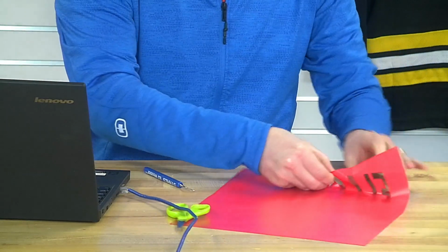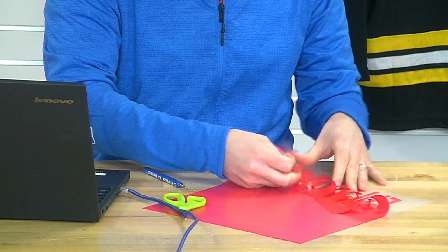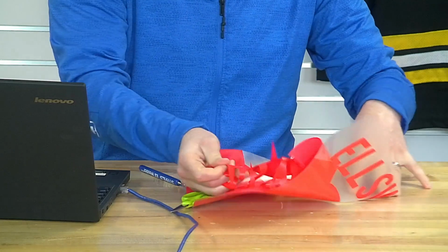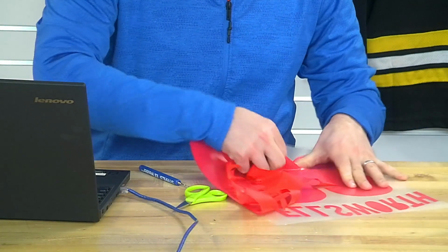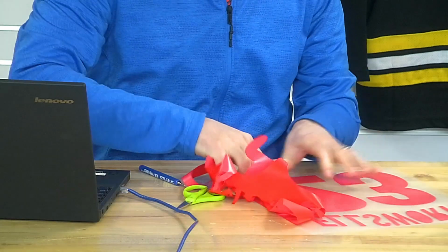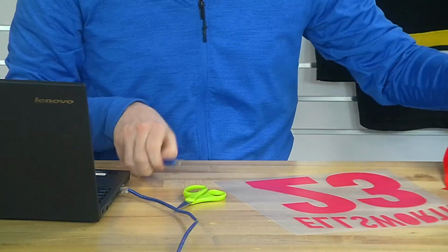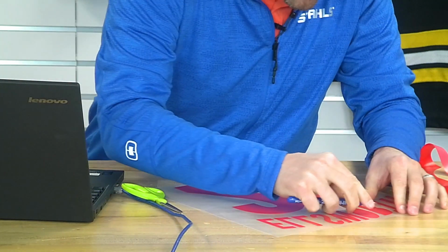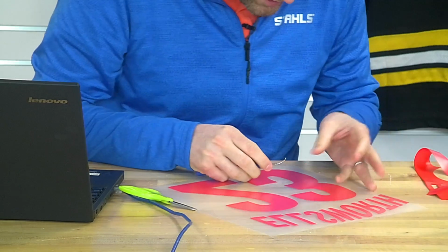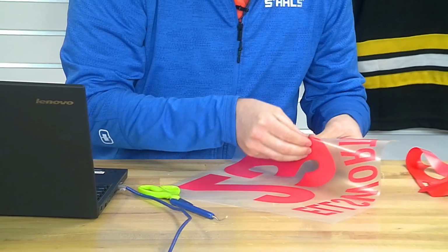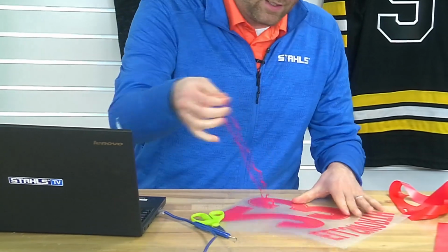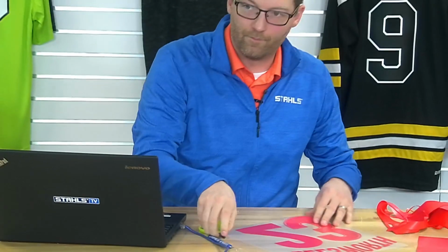Again, ThermoFilm, very quick, very easy. It's a little thicker, so you don't get the breakage as well. Usually when people weed this, they understand the labor savings and they don't want to use any other product to do their athletic names and numbers, because you don't have to really be careful with it at all if you have it cut accurately. So that's how quick it can be to weed ThermoFilm. Also, because it is slightly thicker, it's a lot easier to get a hold of with the weeding tool, or even if you don't want to use the weeding tool, just with bending the material, and if you have decent fingernails, being able to just grab it and then weed it. Even thin stuff like that, not breaking.